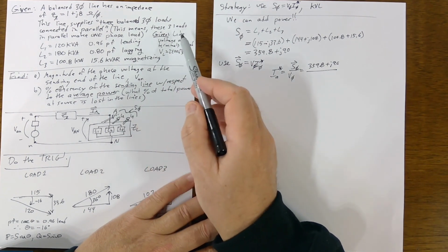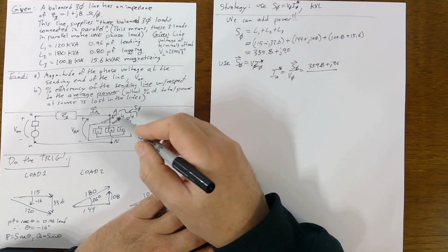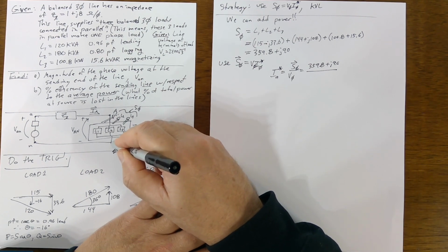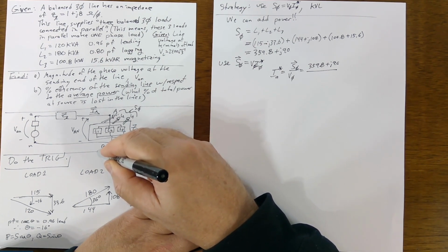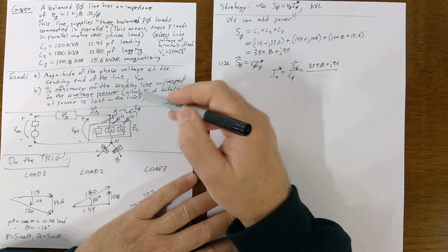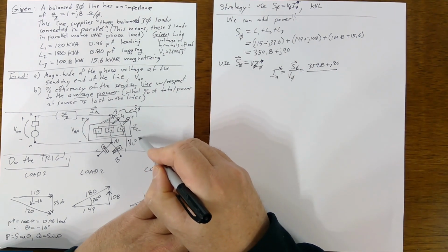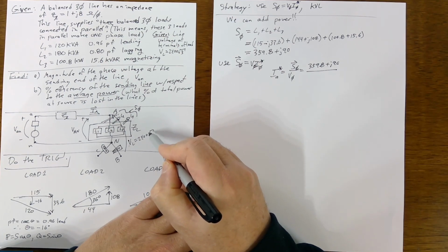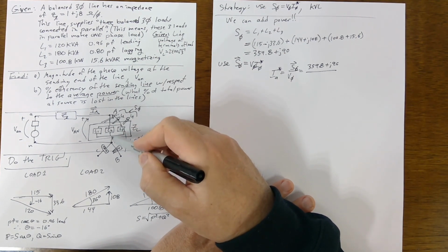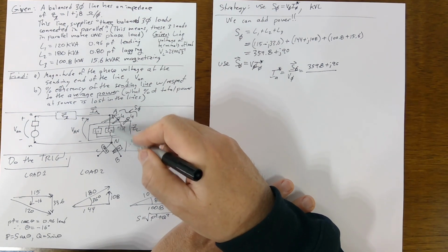They're telling you the line voltage, which means line to line, at the terminals of the load. So they mean A to B. There's another big parallel box of goodies in there, and then another big parallel box of goodies out to terminal C, and this is out to terminal B. They've given you VL is 2400 root 3, but we need the VA. We need the phase part of that.